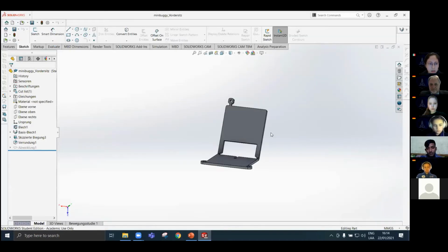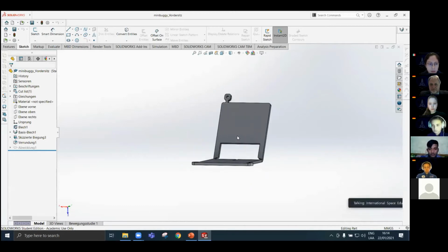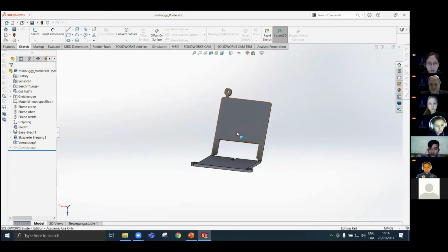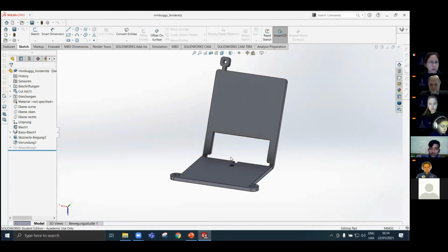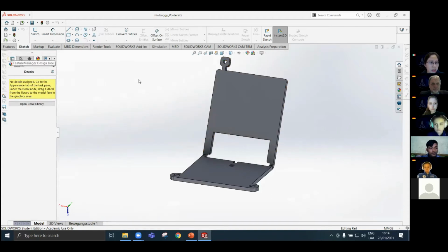Okay, so I'll go to my SolidWorks and I will start with this sheet. You can see it's empty. I have 2 options to add my logos on it. The first one is to go to this left part of the menu that we already know, and click on the appearances in the display manager. And we have a second icon here. It is called View Decals, and you can see it's a little bit like a cylinder with a logo inside. So I'm going to click it.